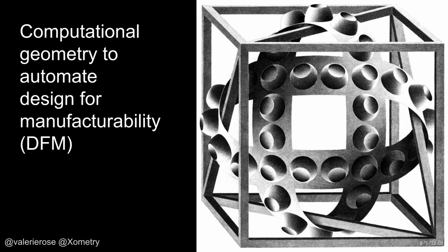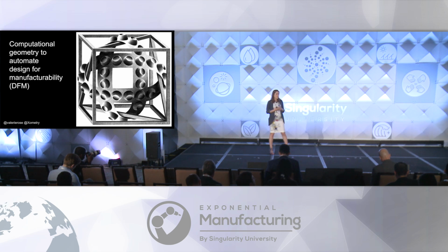That's not true for custom parts. So to price a custom part, you need to understand the geometry in depth. And there's a term called design for manufacturability. Means, can this part even be made? Right? It's pretty easy to design a part that can't even be made in CAD software. For instance, if it has confined hollows or has unreachable surfaces, it can't be machined with straight tools. So instantly connecting supply and demand requires detecting all of those cases and how they impact the price.